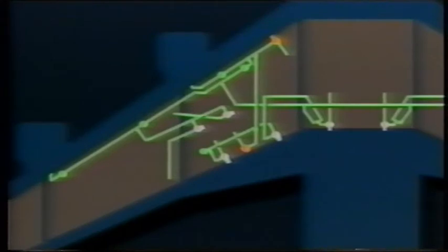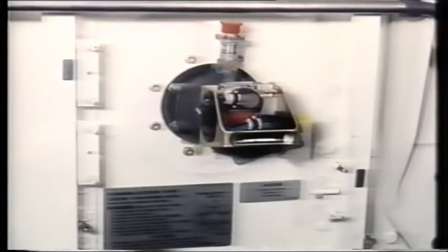The boost pumps for the inboard main tanks are mounted through the front and rear wing spars. The boost pumps deliver pressurized fuel from the main tanks to the cross-feed manifold. Two override jettison pumps are in the center wing tank and in main tanks 2 and 3. They are mounted through the wing rear spar and supply high-pressure fuel to the cross-feed manifold.